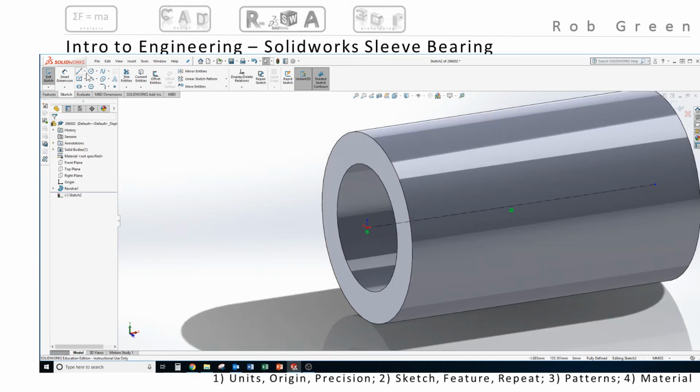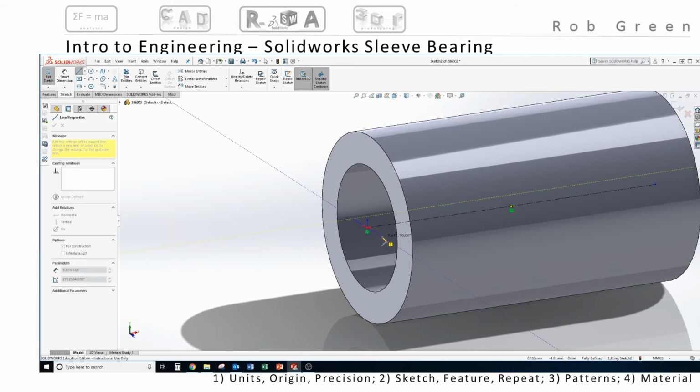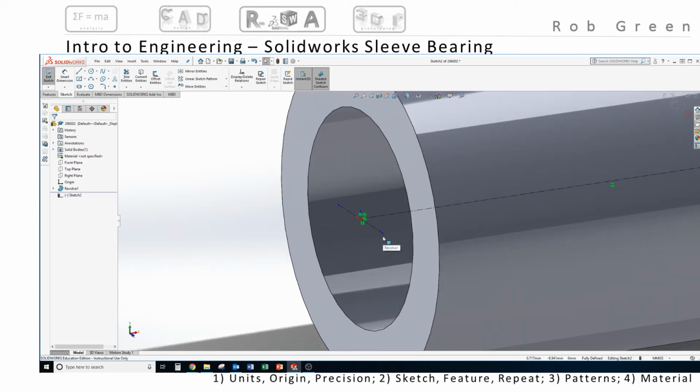I'm now going to draw a different type of construction line. I'm going to click center line, and I'm going to use this option called midpoint. And now I'm going to click on the origin, and I'm going to move my line to the right and down a little bit, highlighting that it's kind of in the vertical Y direction, and click it into place. Quite frankly, I don't really care what the length on this is. I'm going to use this as a construction line.